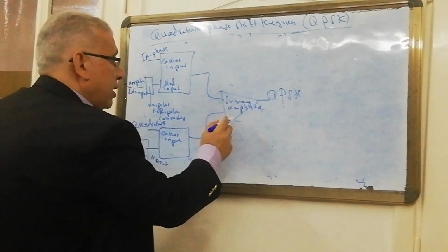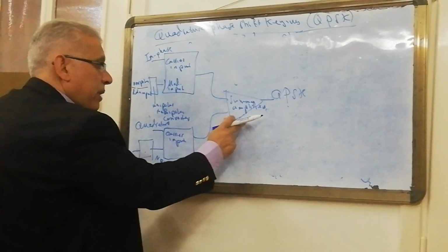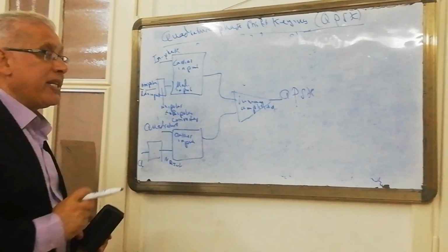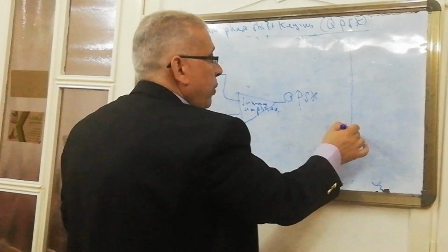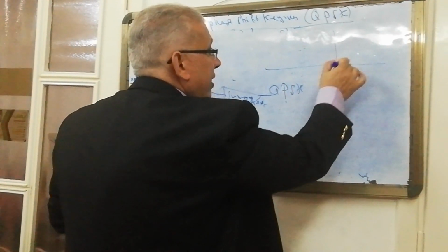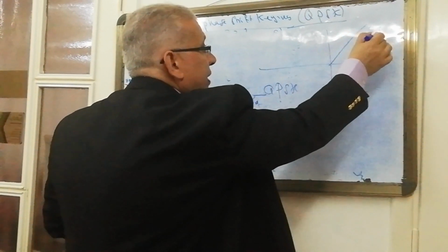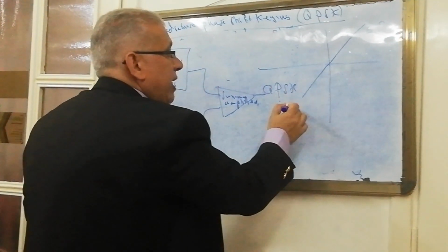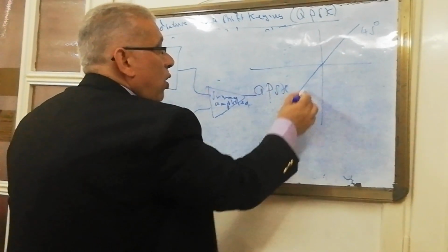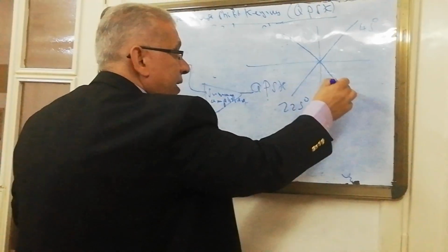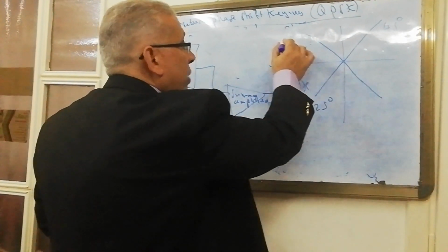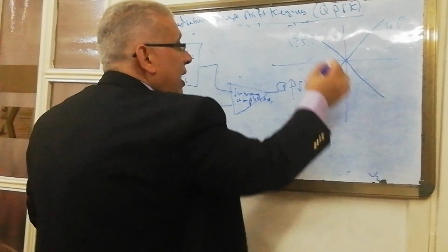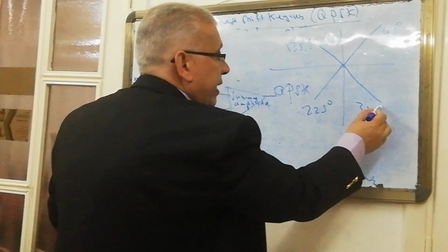In this traditional case, we will have a problem. The receiver will find it difficult to distinguish between 45 degrees and the opposite one, which is 225 degrees. Also, it will be difficult or impossible to distinguish between 135 degrees and 315 degrees.